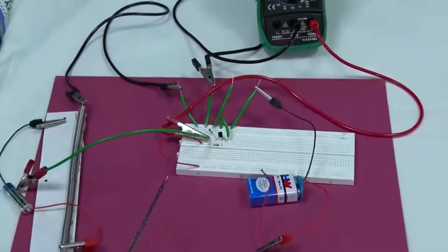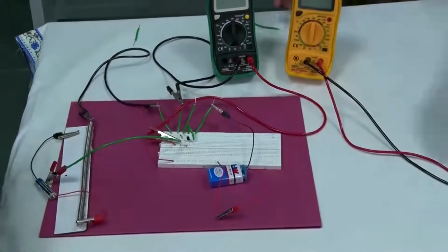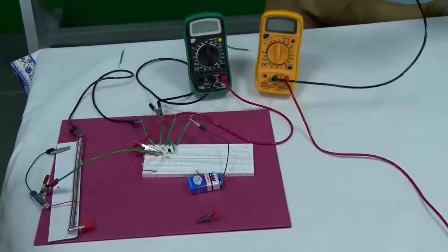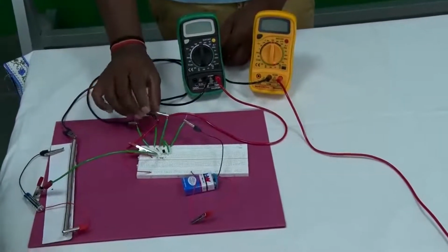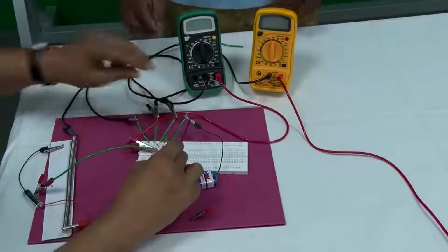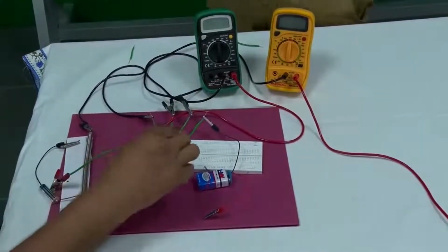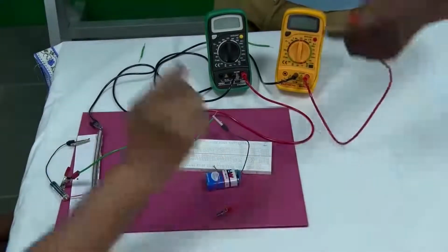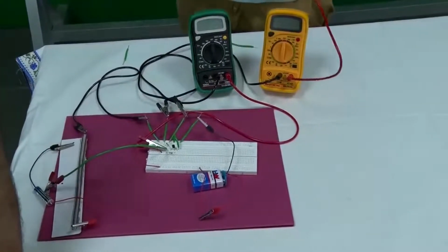Then the output side. In the output side, once again the black terminal should be grounded, 0 potential. So, see how the circuit is implemented nicely. This is also at the same potential. All those negative terminals, all those black leads, they are joined together. Okay. And the positive red terminal should be measuring VO, the collector. So, it has to be directly connected to the collector.